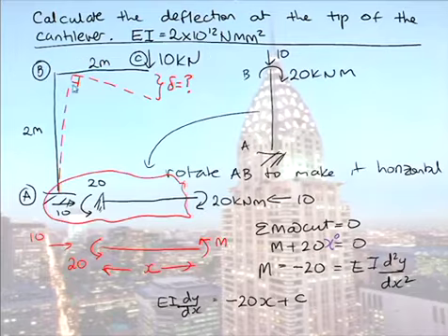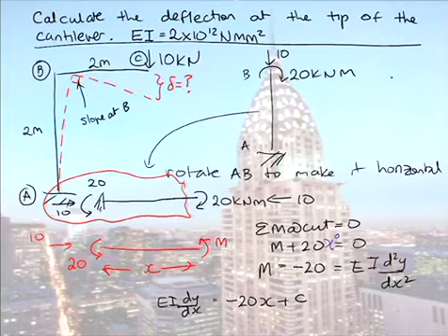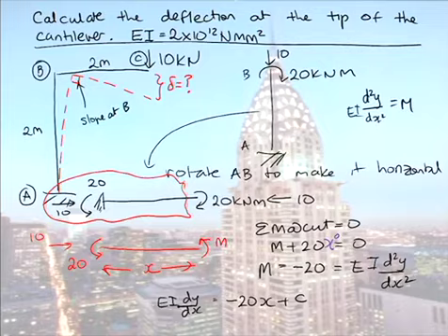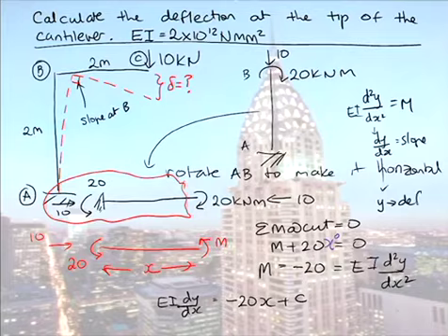So I got as far as analysing beam AB, the vertical component, and I said I'm just going to rotate it round because my mind, and I think most of your minds, work better when something is horizontal. So what you're seeing here is the beam AB rotated 90 degrees to make our life easier. And what I'm after is the slope at B, and hopefully you remember our equation, d2y/dx2 on EI is equal to our moment. When we integrate that once we get dy/dx, which is our slope. And when we integrate it a second time we get y, our deflection, which is what we're after.